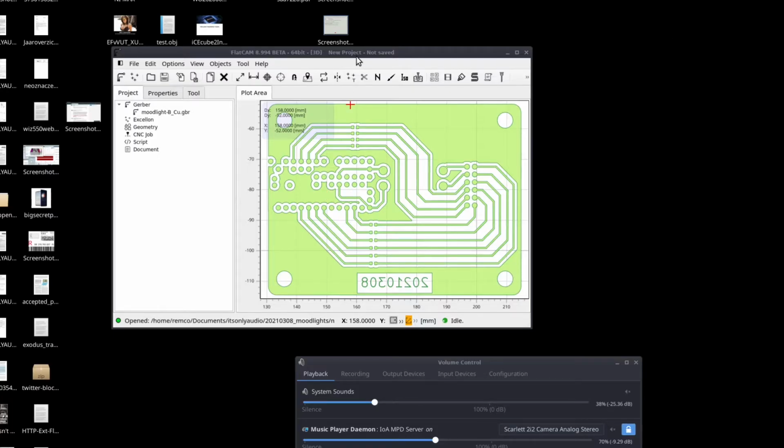So, as an FYI, we have FlatCam running under Linux. This wasn't easy. It's a Python program, so you would expect it to just work. However, it depends on Python Qt4, and that last ran, I think, in Ubuntu 16.04. So there are two options to get it running in modern Ubuntu. This is Ubuntu 20 something something.